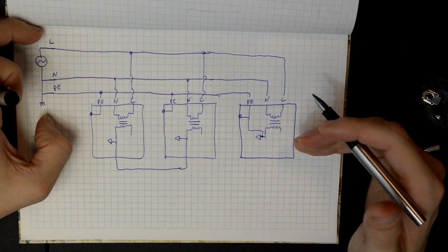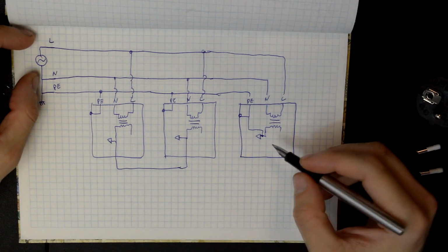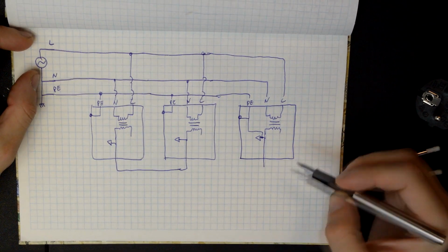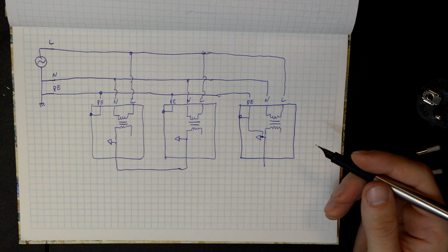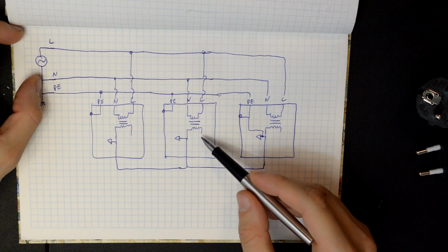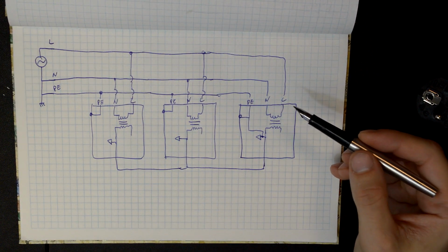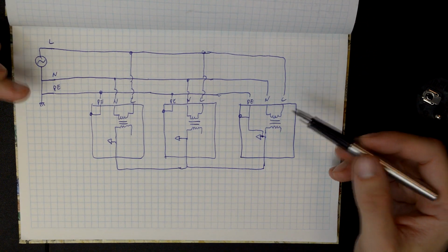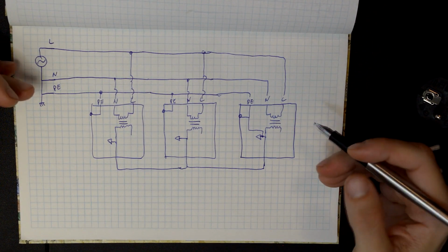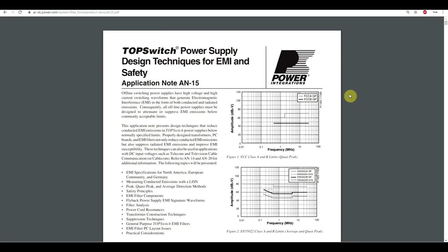Since all the measurements you want to make should have a very stable reference, which is the earth ground. Now, when you connect your oscilloscope to any other circuit, like the power supply, you're connecting this completely floating ground to the earth ground. Now, this normally should not be a bad thing. I mean, this protected earth is there to protect you, so it's supposed to do good things. But is it?